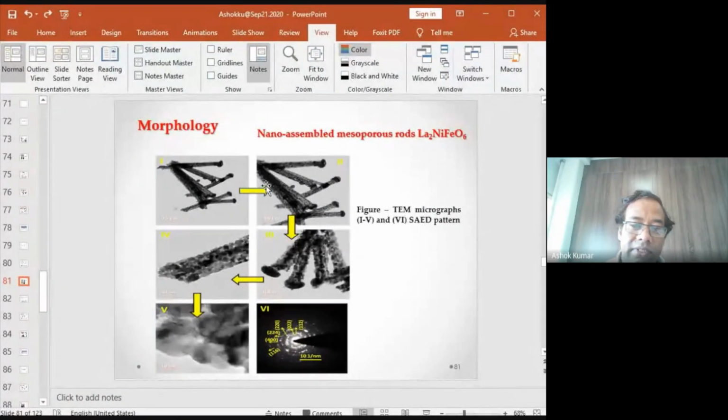Okay, so then in this high resolution picture, you can see it further zoomed, and this is selected area diffraction. You can see here this dotted kind of pattern, that means textured material. And don't be confused by textured material: like in a powder, you have all the planes oriented in random order. Textured material means some of the planes are missing, or the material has been oriented in some particular direction.